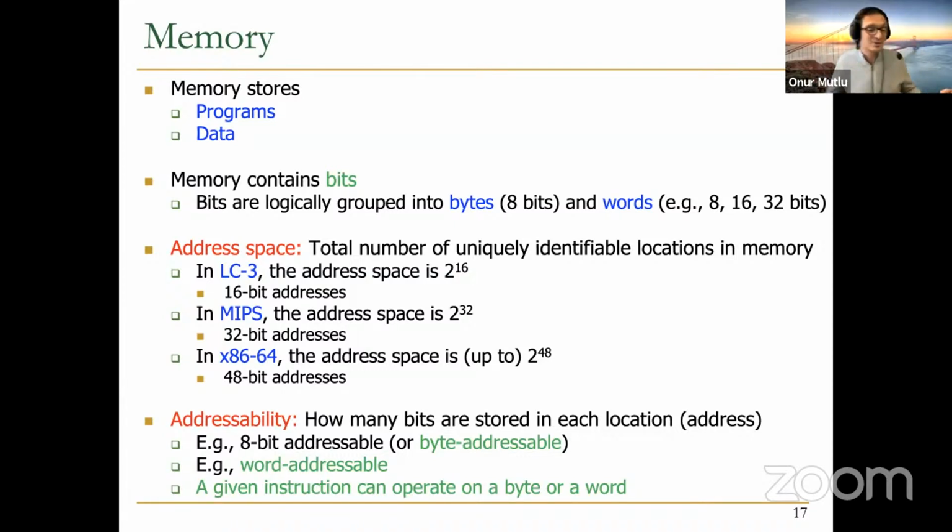Underneath, I can do that. Nobody is telling me I cannot, because I get better performance by getting 128 bytes from my memory right away. In each location, I store 128 bytes, but I pick only the 8 bits that the programmer wants using a multiplexer. You know the multiplexer: you get 128 bytes and pick one of those bytes. That's a 128 to 1 multiplexer. Okay, so hopefully this is clear.